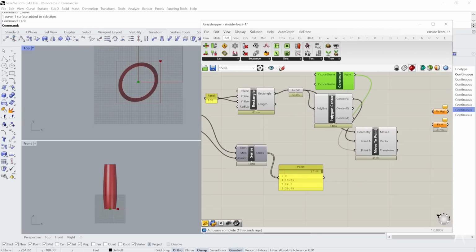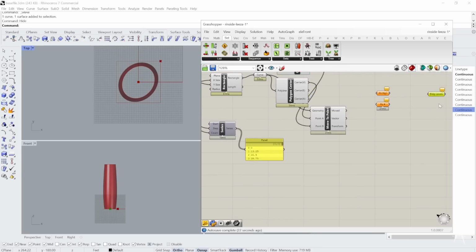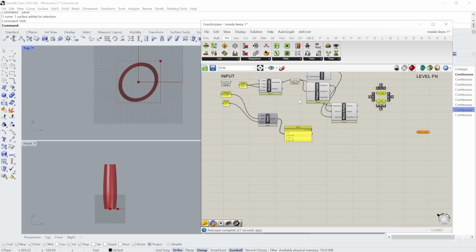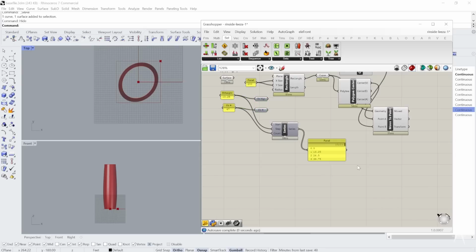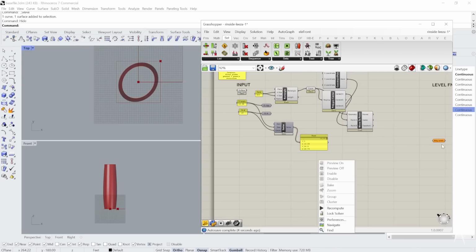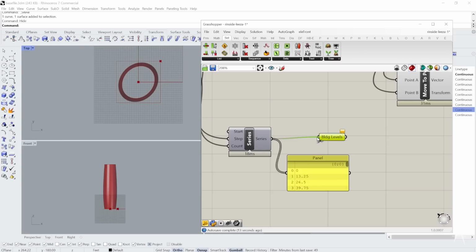All right, so these are going to be my levels, and I've already placed a value for that here. And we're going to pull these two values back, just so we have that labeled, the floor height and the floor count. We're going to take this value and plug it into building levels. Again, we're giving lots of space, thinking about productivity and working with others as you work on these codes. We're going to plug that into our building levels. This is pretty much everywhere there's a level.